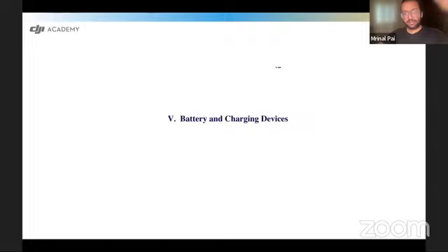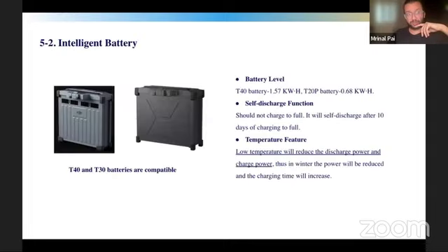The battery, like I said, you can either charge it if there is electricity access, then you can plug it in and charge it in 10 minutes. In case that's not possible, some service providers require a generator. Have a generator on site, have a drone, have 2 batteries, keep charging the battery, 10 minutes it will charge, change the battery, keep flying, right? So that's also an optional equipment available with the drone.